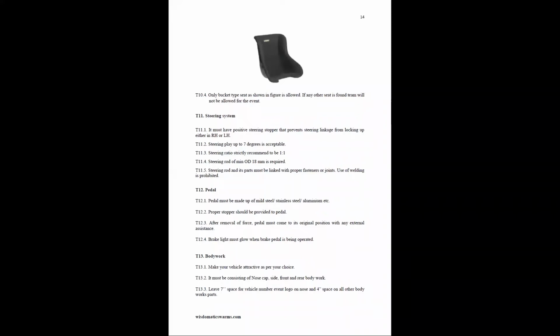So the pedal must be made up of mild steel, stainless steel, or aluminum. That's your choice. But proper stops should be provided to the pedal also. And it should retract once pressed. It should come back to its original position without any external assistance. Once you have pressed your pedal on the brake pad, the brake light should glow.